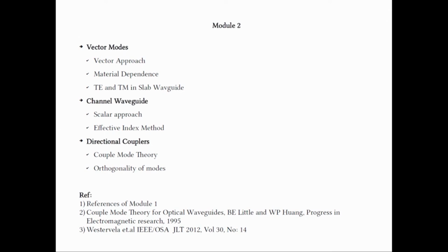The coefficients of the coupling equations are Kij, which consist of all the parameters of the structure, like the spacing between the waveguides, the waveguide design, the refractive index contrast, the operating wavelength and so on and so forth. In particular, the spacing is a very sensitive element. As you increase the spacing, the coupling reduces and more length is needed to couple the waveguides.